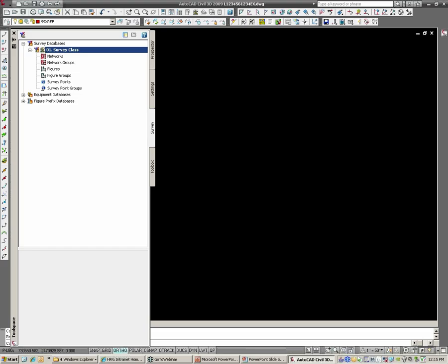The RW5 really keeps a recording of which points you're set up on and side shots you made from that, the back sight, so on and so forth. And then if we're getting it from another firm, you're usually going to get it in a text file. So those three options all can be imported into the survey database.